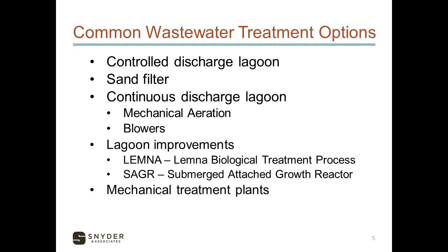As you move up the ladder to a little bit more technology, you might have a continuous discharge lagoon where each day you have water in and water out. Oftentimes these require mechanical aeration or possibly adding air with blowers. Some new technology that we've seen in the last 15 or 20 years include technology like a Lemna system, which is a floating cover to keep the water warmer in the fall and spring. That would be supplemented with blowers for aeration, along with what they call a polishing reactor, which is just a slightly different configuration of air in a concrete tank after it leaves the lagoons.